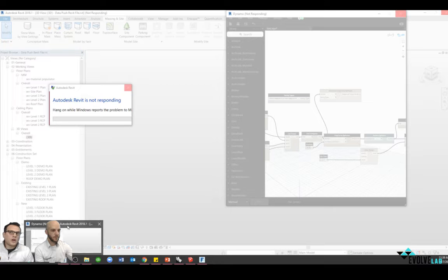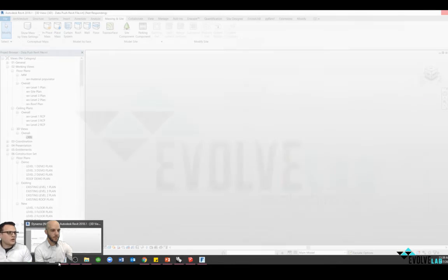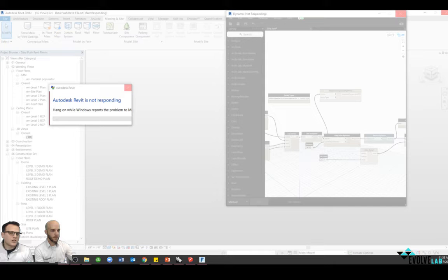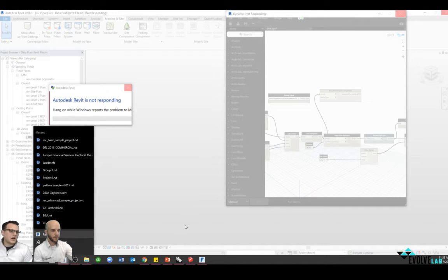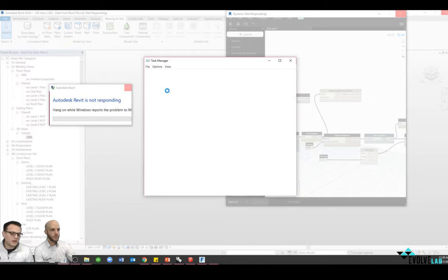And what ended up happening is after purging those two things out of their model, and suggesting using something like Illustrator or InDesign for manipulating the renderings, we were able to cut their file size in half and increase the model performance so that it was actually responsive, rather than having all these really long delays and latency issues caused by importing DWGs. It's just a really bad practice. So thanks for pointing that out, Andrew.